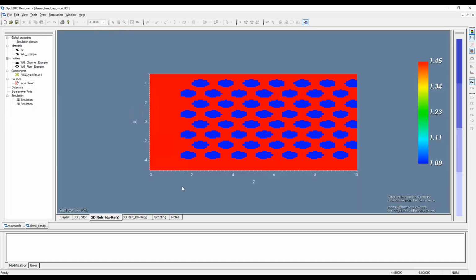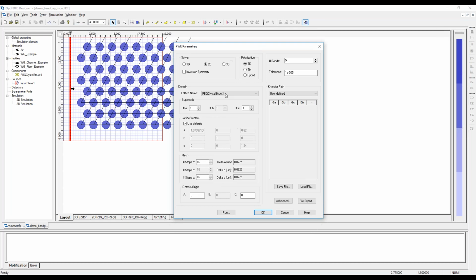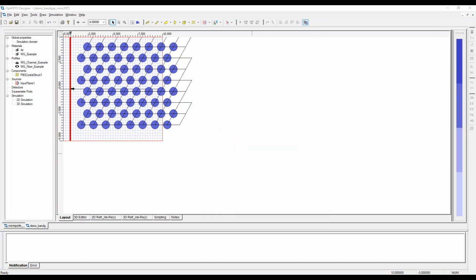And then look at the refractive index. So we have the high index silica structure with the air holes in blue there. And now it's basically as simple as going to the plane wave expansion band solver tool, and I can choose a path hexagonal because it's a hexagonal periodic structure. I can increase the mesh resolution here a bit if I'd like. Maybe the tolerance. I'm just matching the ones I did earlier so I don't get any surprises.